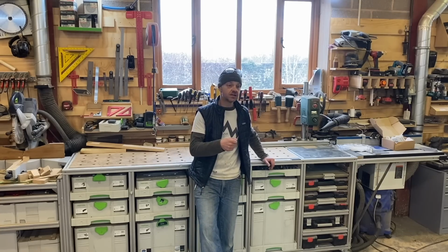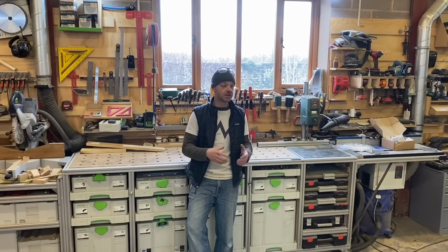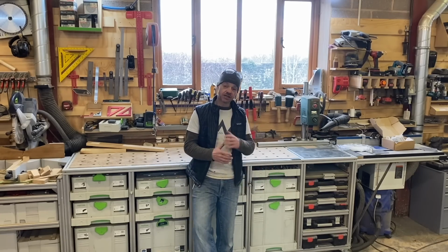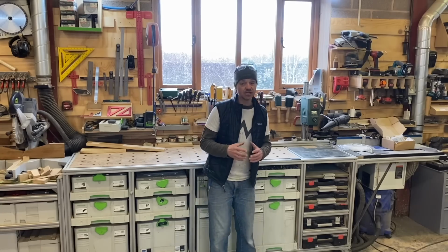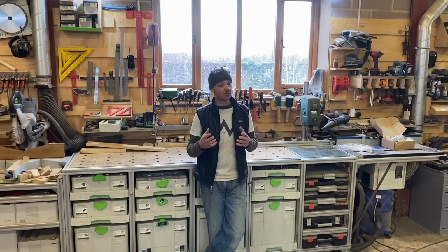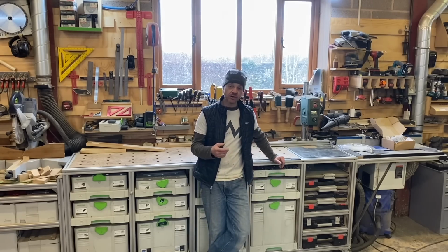the process of drying. I even go to clients' houses sometimes and I take moisture readings if they live in a big old manor house or something that's a bit damp, try and get the tables or big bits of furniture, wide slabs, try and get them in their house around about the right humidity. I think Wagner call it EMC. So I kind of check that. That's all done on an iPhone.